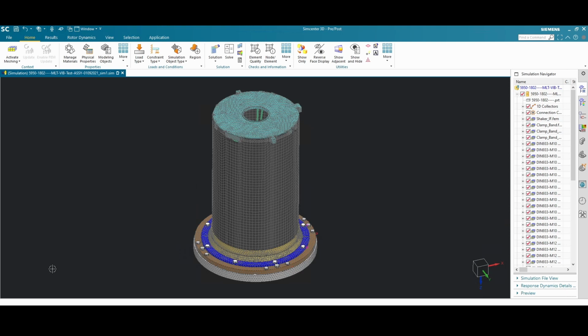Even after remeshing the model, Mars recognizes the bolts in each group based on the group name, assuming the name remains the same. Once the text file is imported, Mars updates the bolt element IDs in the analysis to match the load input data. I will now generate a text file containing the exported information and then explain its contents.